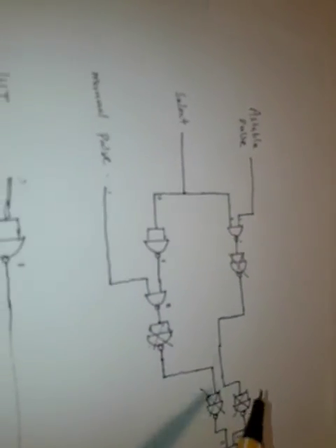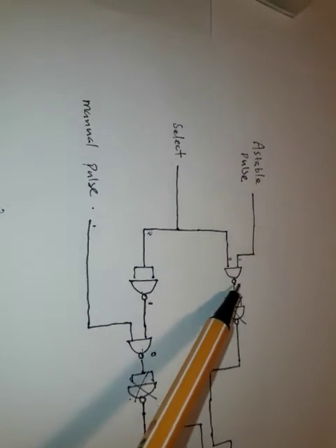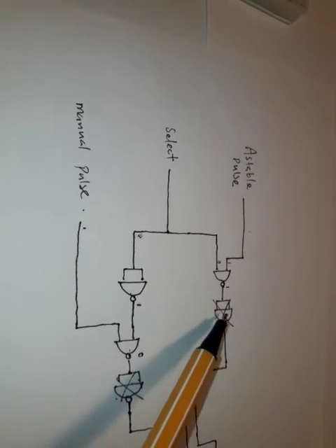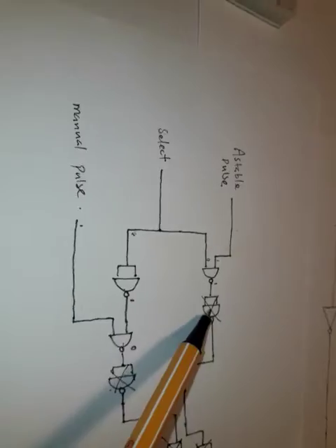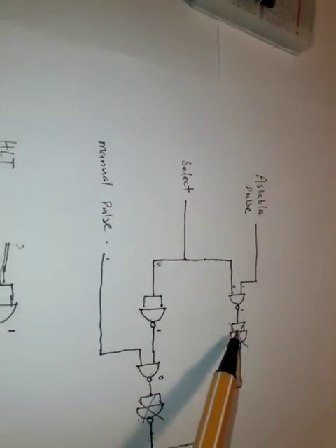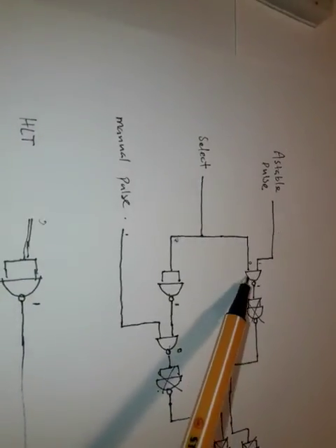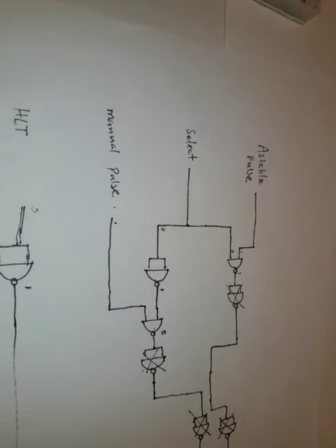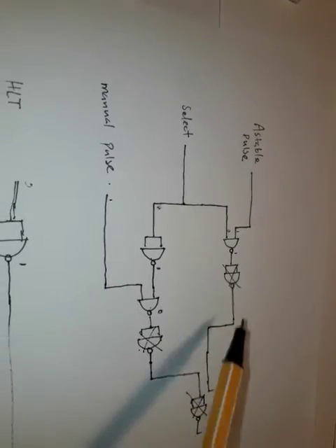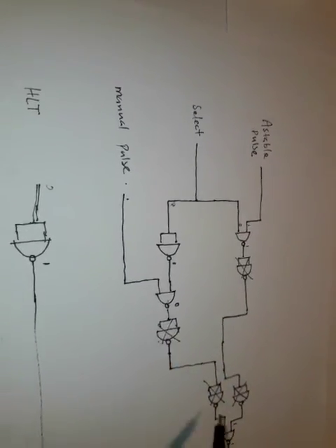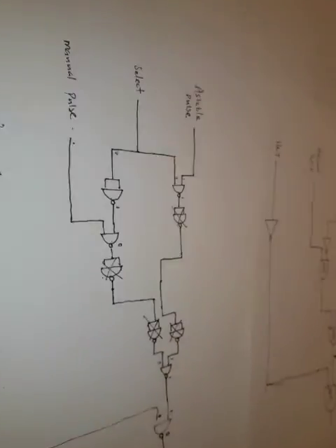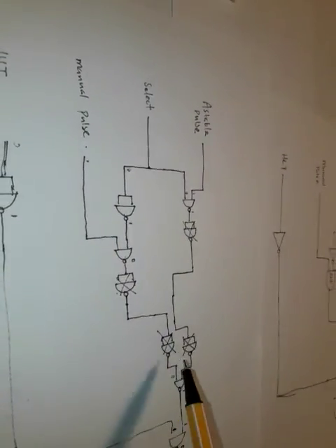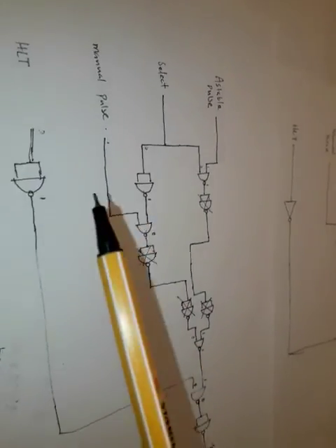But if you see, if you have high here, and this is an inverter, as we can see here, when you convert from high to low, you're going to convert from low to high again. So which means we don't need these 2 NAND gates, and the same is applicable to this point also. Therefore, we only need 1, 2, 3, 4, 5, 6, and 7.